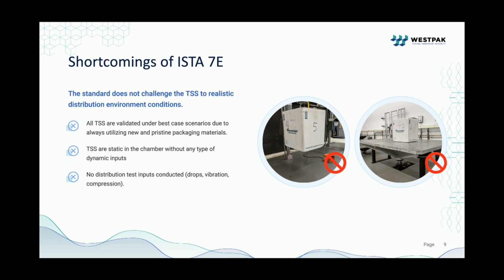But if you introduce anything like a drop or vibration, then you're challenging the shipper. Maybe if you're shipping with insulated EPS, the EPS will crack. When you do vibration, your products, your components, everything will get heated up just because of the energy associated with it. So the study is basically saying that there is an effect on your thermal studies from these physical tests, but let's find out how big of an effect it is.